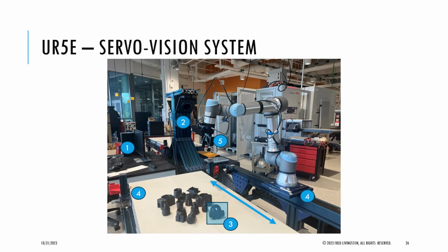I'm going to use this as the Z camera, which has an RGB, it's a stereo vision system. So it has 2 RGB, and they compute a point cloud, which you can call PCL, which gives you X, Y, Z coordinates here. So this is a blob here, and you can cluster these together and find the center of the object there. But we're just going to look at, we want to detect this box here. I just want to detect the edge of that box here. And that's where we're going to pick it up. That may not be where you really want to pick it up.